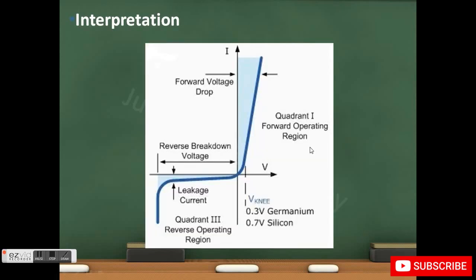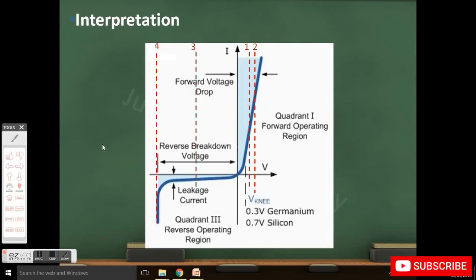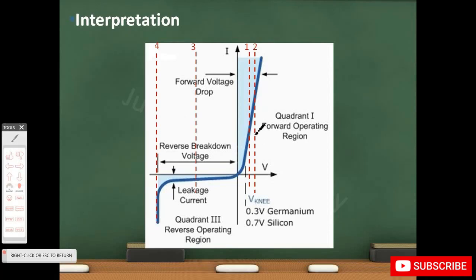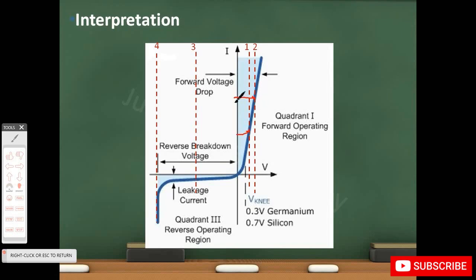Now, let's look at another graph that we use in lecture 7 when we talk about diodes. So again, to interpret this graph, we'll take few points. 1, 2, 3, and 4. So from point 1 to point 2, when the voltage is positive, as you can see, we only increase a little bit of the voltage, but there's a dramatic increase in the current. When we continue to increase this voltage, the current will just boost to a very large value, limiting the voltage from further going up.